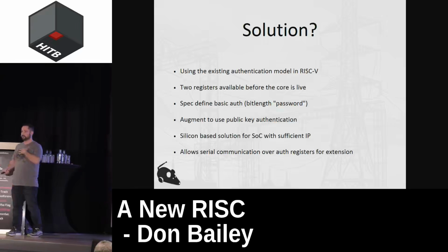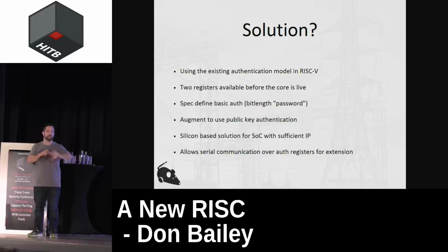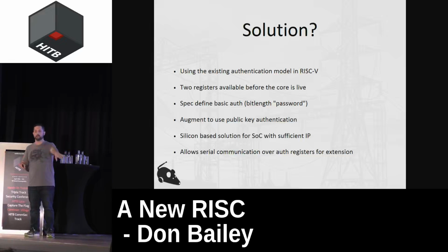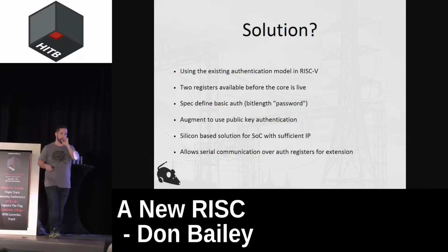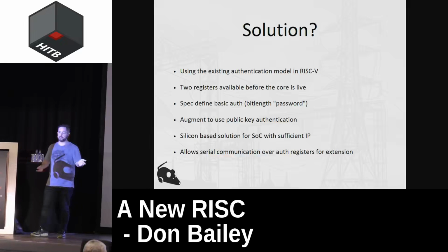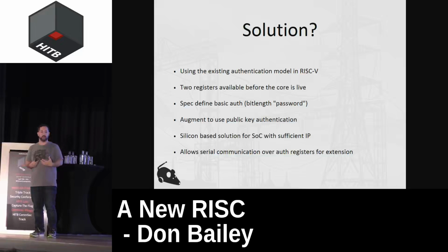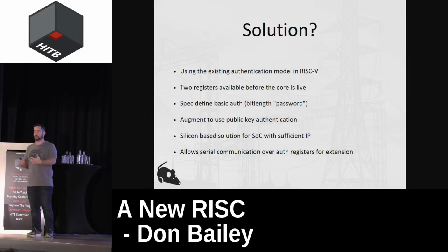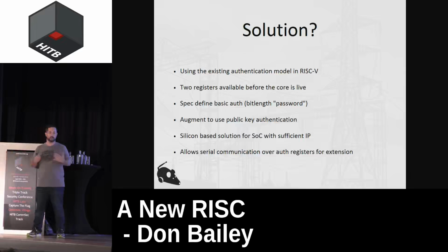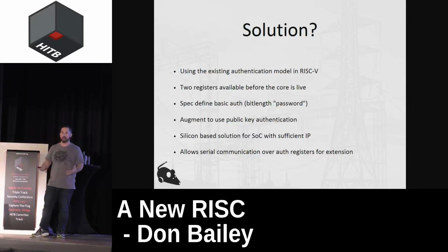As engineers, as security guys, you never want to say, oh yeah, go and disable JTAG. You should never have JTAG accessible in production. That's actually bullshit. You should never tell anybody that. And the reason why is because it's not usable, right? In the real world as an engineer, I want to be able to access JTAG when a system is failing and it gets shipped back to me and I need to figure out why it's failing. That's exactly why JTAG is there. I don't want to disable a feature that's going to allow me to learn more about why my product is a problem, right?